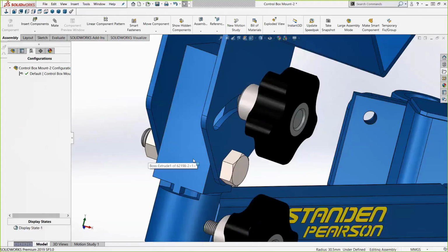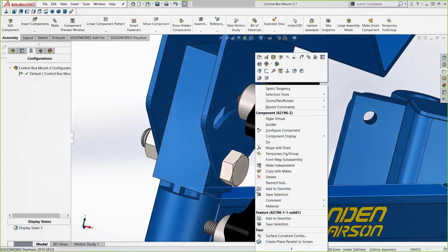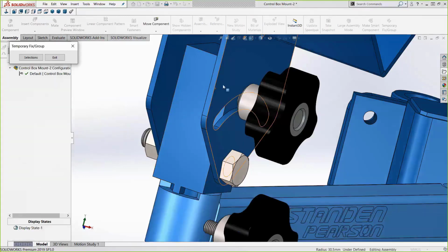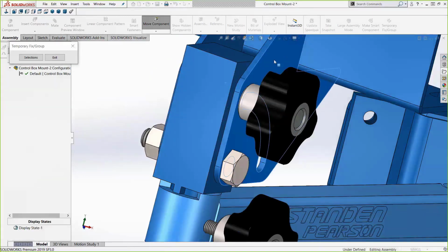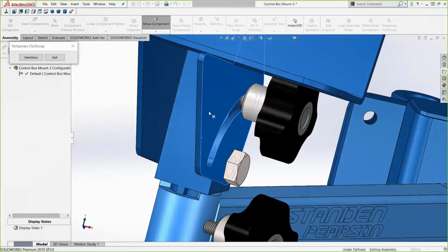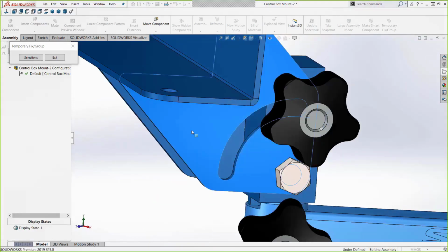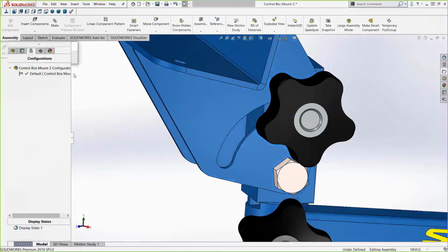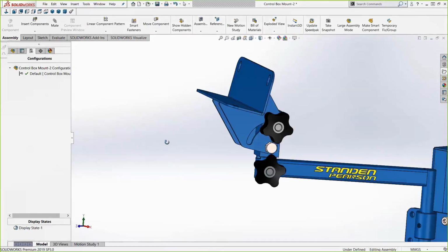I'm going to go ahead and set that to free, and I kind of contain that movement of that cylindrical face within that slot. As we move that around and let that free, it's staying within that slot there. And really easy, again, to access that, to make any changes.